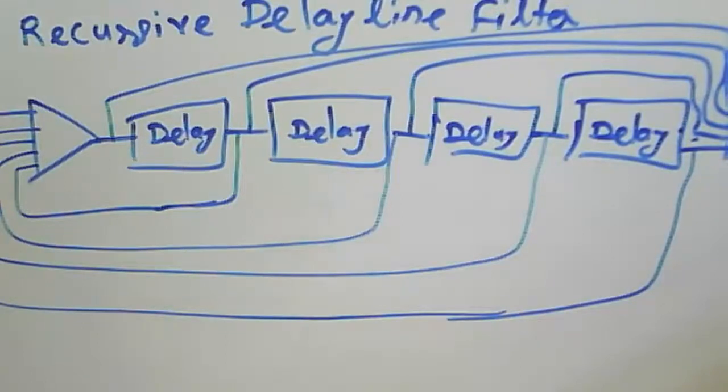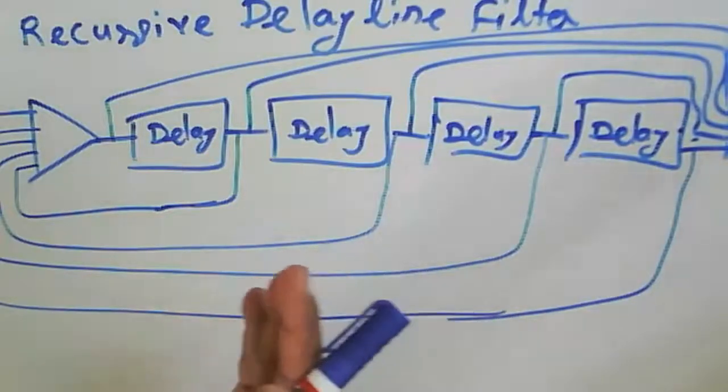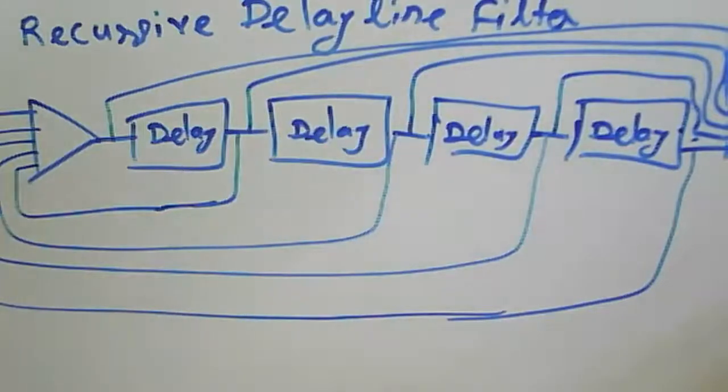And again we use fewer delay lines to avoid the clutter. So we can remove large discrete clutter echoes, interference pulses from a nearby radar, as well as deliberate pulses, that is the jamming pulses, or whichever pulses come from a nearby object, through this particular filter.